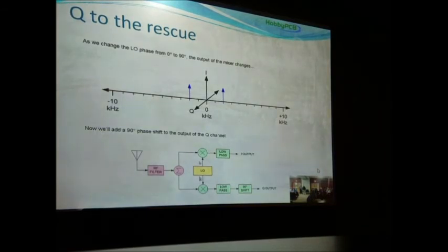It has some pretty serious limitations. It's designed so that it's only working on one signal, and that signal's coming in at a high signal to noise ratio without any interfering signals. And that's why they can make that thing useful with 12 bits. 12 bits is about a 60 dB dynamic range.